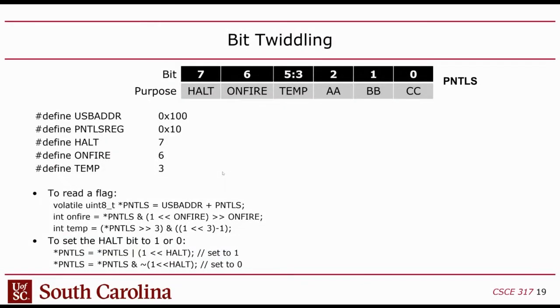Okay, so here's another example. Going back to the example register, we've got some bit fields here. It's an 8-bit register, labeled PNTLS. That's just a made-up name, but it would be like a name that you might see in a data sheet for a register, because usually I/O registers are individually named.